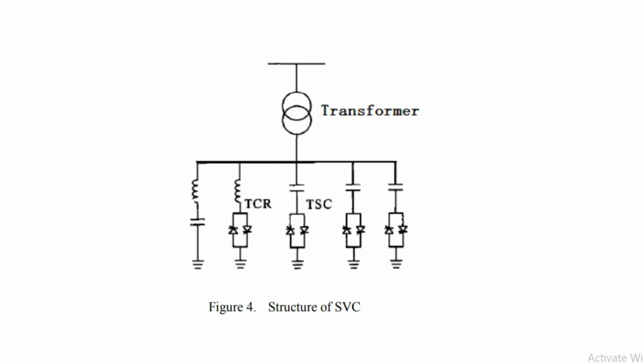Okay, and if you see the static var compensator structure, it consists of thyristor controlled reactor (TCR) and also thyristor switched capacitor (TSC) and also some filters and control algorithm. This all comes under static var compensator.